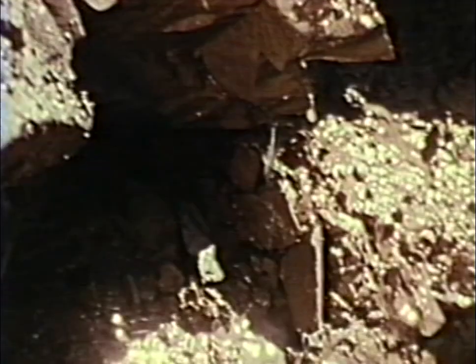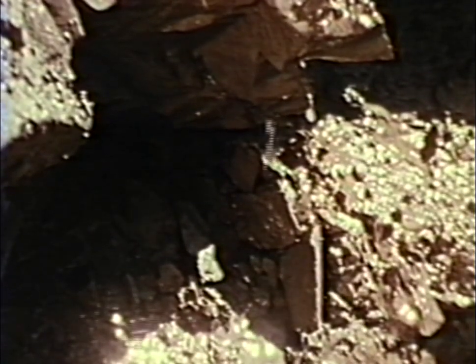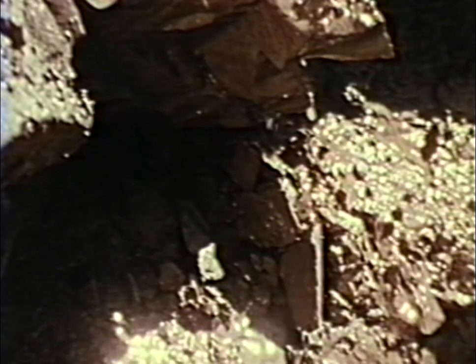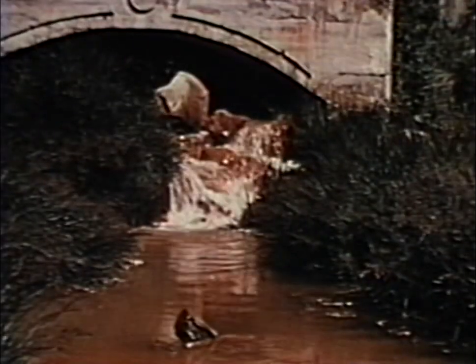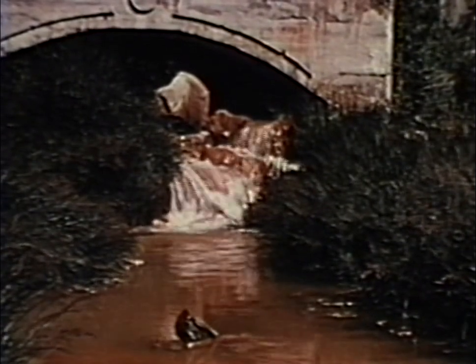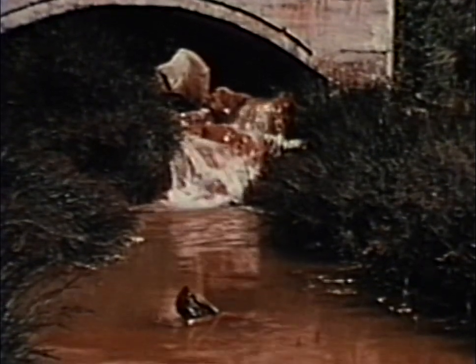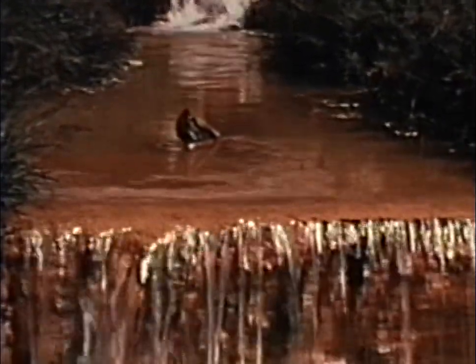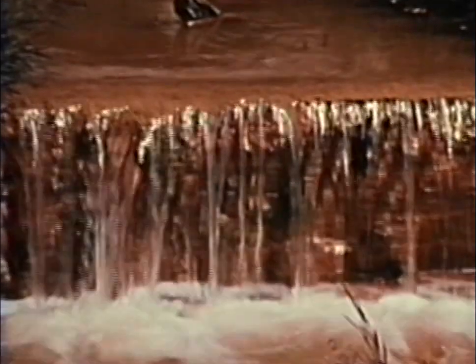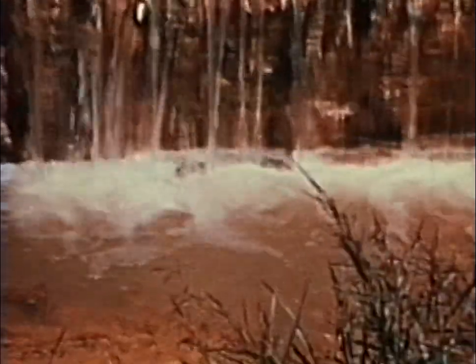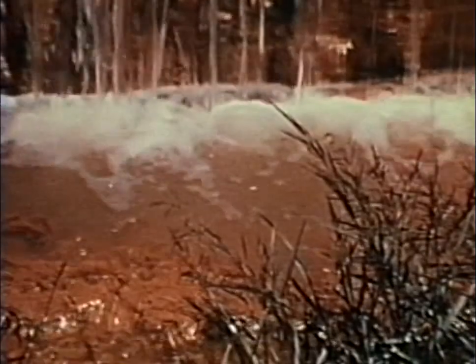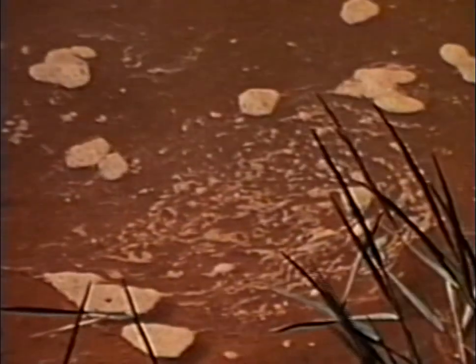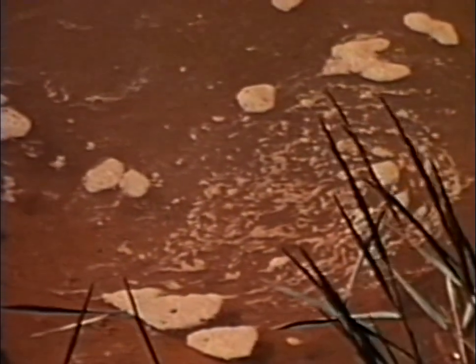In some areas, the effects on groundwater are slight. In other areas, the water level drawdown spreads far from the mine. In the eastern United States, groundwater flowing into coal mines undergoes chemical changes as it becomes aerated. As it picks up iron and sulfur and becomes acidic, the water becomes an environmental hazard. Each year, billions of liters of acid mine water drain from coal mines into streams and rivers.